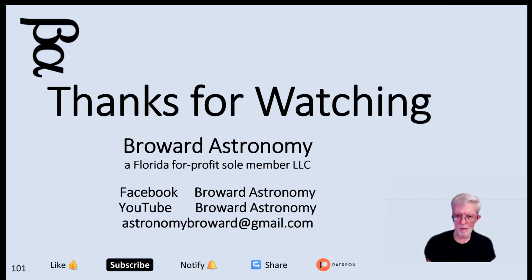The best way for you to see this is go to a place that has outdoor LED lighting and record video of it. What you will see is light and dark sections of what to your eyes looks like continuously bright LED. That's because the frame capture rate of your camera, being 120 hertz these days, is getting out of phase alignment with the PWM refresh rate of the LEDs. So it looks dark because you're predominantly seeing at that angle it's off as opposed to on.